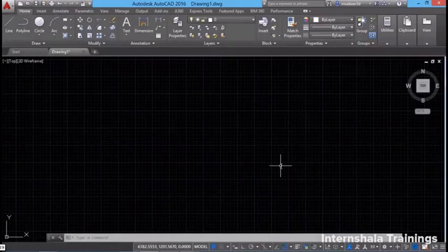In this video, I'll introduce you to points, circles and arcs in detail, and we will see the various methods to construct these objects in AutoCAD. We will start with a point. A point in AutoCAD is a node which will act as a place marker to construct so many other objects. A point has absolutely no size and it can be constructed using a variety of options.